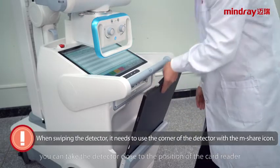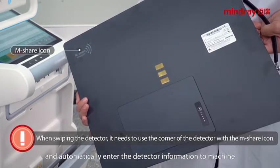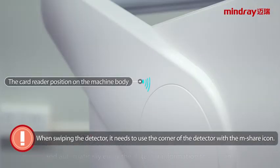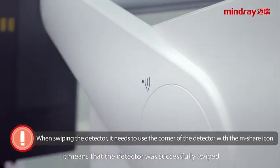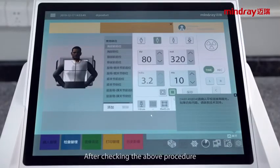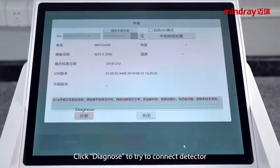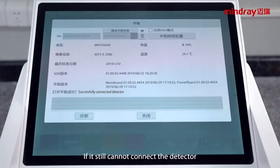If there is an exception in the above operation, you can take the detector close to the position of the card reader. Swipe the detector again and the detector information will be automatically entered into the machine. When you hear the sound of "Di", it means that the detector was successfully swiped. After checking the above procedure, you can try to click Detector State. Click Diagnose to try to connect the detector. If it still cannot connect to the detector, please contact MobiEye customer service.